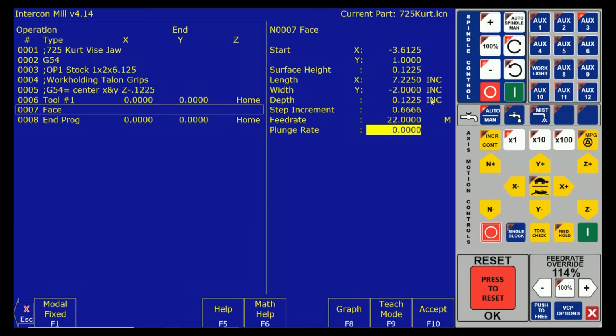So question on chip load: if you had a tooling, would that information be on the box? Okay, the question is, where do I get chip load from? I am going to feed you chip load early on. For my classes, I'm going to provide, like this 5 thou, I'm just going to throw that one at you and give that to you.